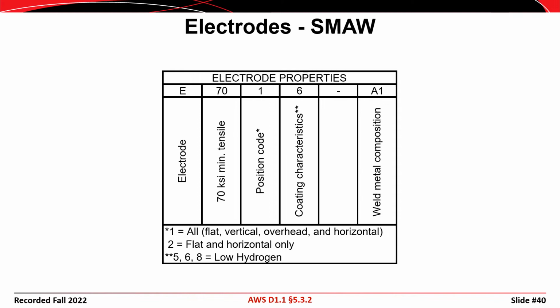Now, I will say one thing about weld metals. The terms matching and undermatched weld metals mean something to us. Typically, when you look at a base metal, say an A572 grade 50 base metal, you would have a yield stress F sub Y equal to 50 KSI, and an F sub U equal to 65 KSI.